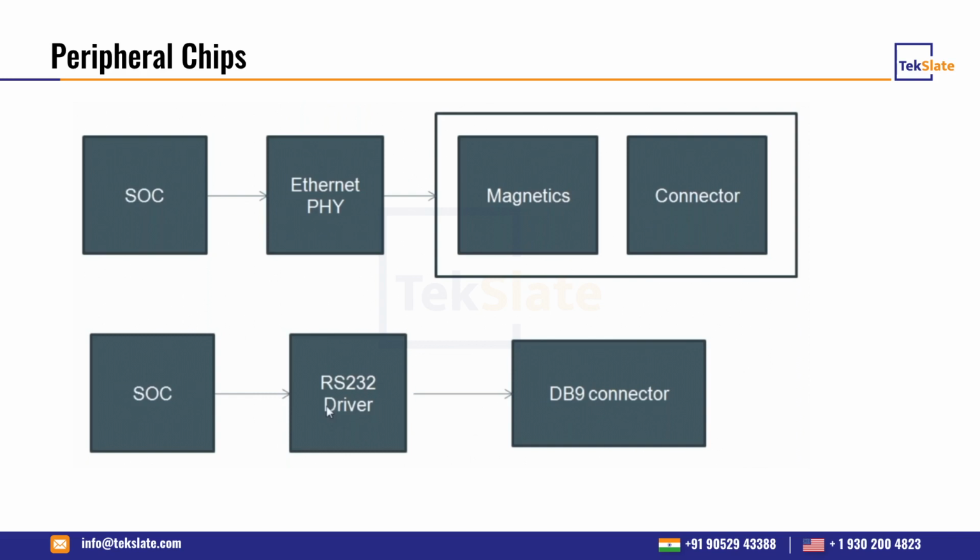One needs to understand what signals are present in this interface, the significance of each signal, the timing of those signals, and the voltage levels of those signals. Similarly, on the SoC end, what is the interface? Is it a standard interface? What is the standard? What are the signals again, their timing and voltage levels? One needs to understand all that and then make this interface design.